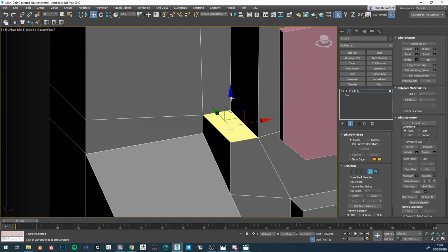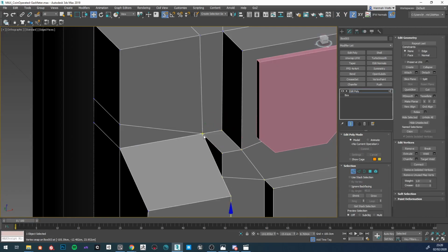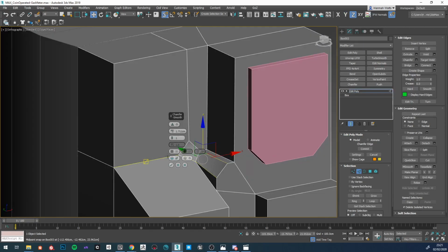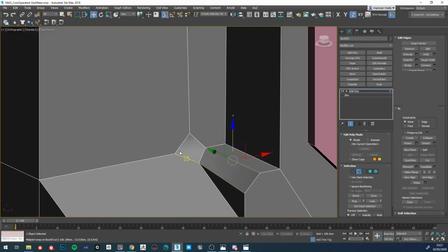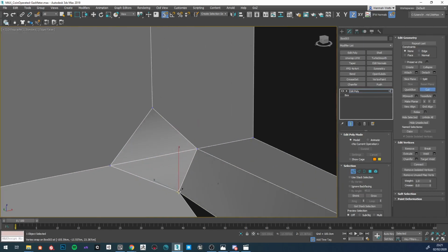The inner corner here, this height needs to be reduced and I need to get rid of that 90-degree blockiness. Again, you wouldn't necessarily need to block in chamfers like this, but doing so here allows me to work out how this curved corner connects to the display screen behind it. And I can begin blocking in the dimensions of what will eventually become the hole for the screen.